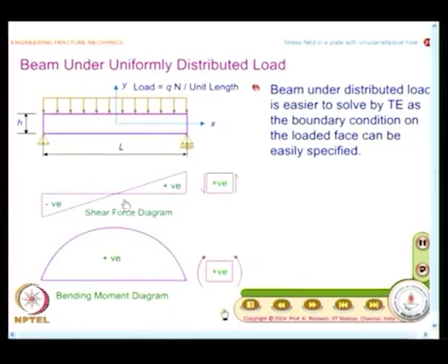In the last class I had shown, when I have constant shear force, then plane sections do not remain plane before and after loading. In fact, it has a variation. Fortunately, it does not interfere with bending. So, bending and shear were uncoupled for normal cross section beams unless you look at deep beams. So, you are justified in extending the flexure formula when shear force remains constant. And what you see here, shear force is not constant. So, bending stress whatever you calculate from your strength of materials will not be accurate. From a mathematical standpoint, the solution will not be accurate, you have to anticipate that.